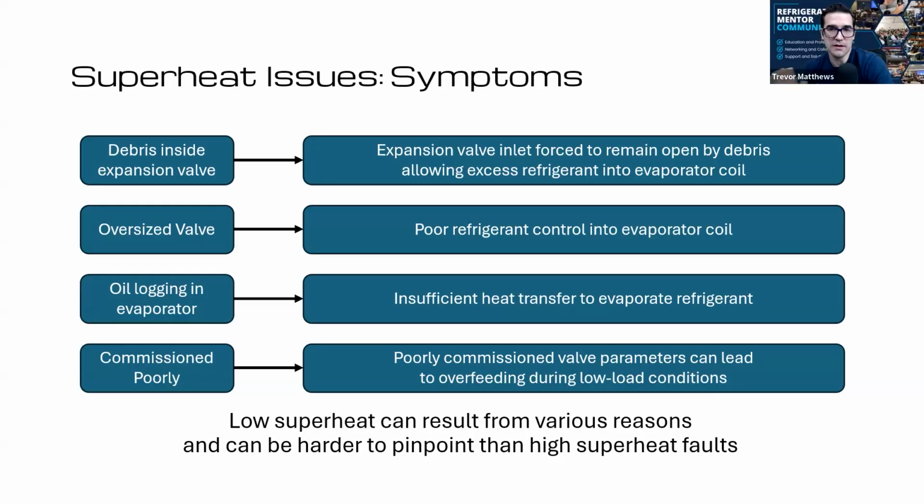Yeah, no, and I totally love looking at the trend graph. So if you're getting into CO2 and you're starting to see more case controllers, I highly recommend starting to learn how to read the trend graphs, because it does take a little bit. Which one should I use and which one should I be watching and monitoring? But for sure, when you're watching the defrost, going into defrost, out of defrost, into defrost, out of defrost, we'll see these consistent things happen as long as it's fine tuned. Because that's another thing that I train a lot in my CO2 programs, is how to properly fine tune it.